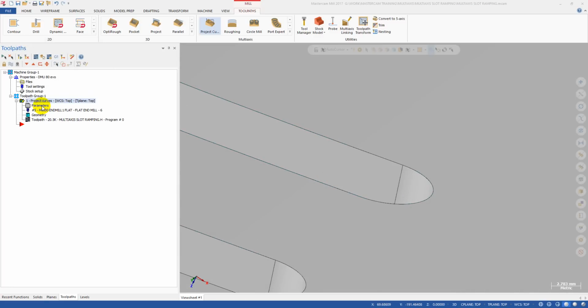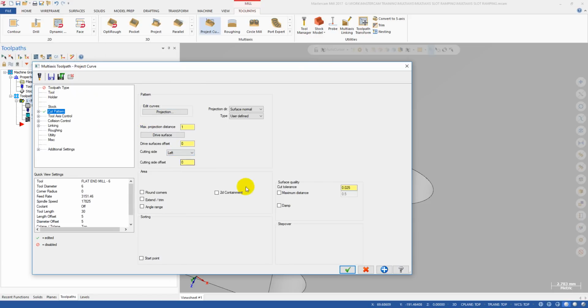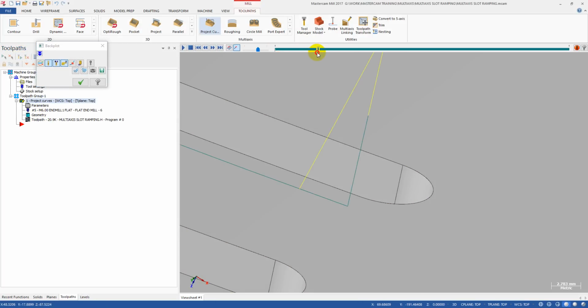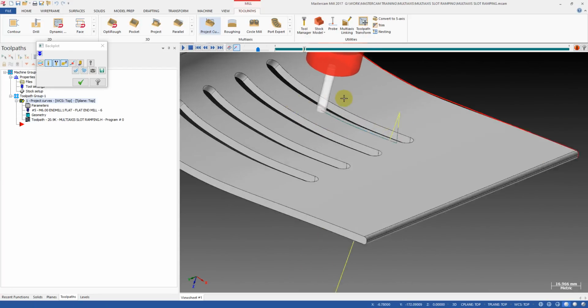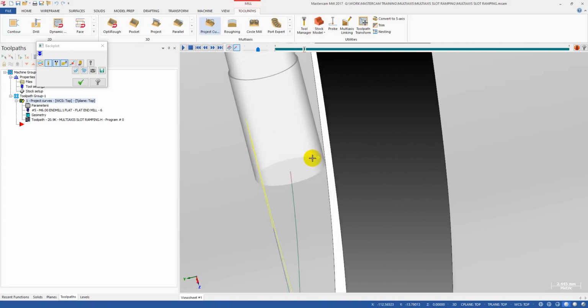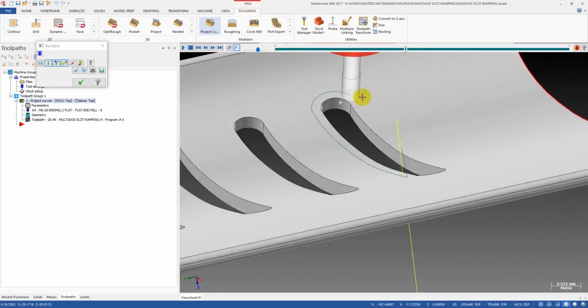We don't want it to cut at the center. I want it to cut on the left side. And you also have the cutting side offset here. That's the material you leave on the side of the curve, like we do in 2D milling. So you can see when I select cut at the side of the tool, and when we select the left, it cuts outside.